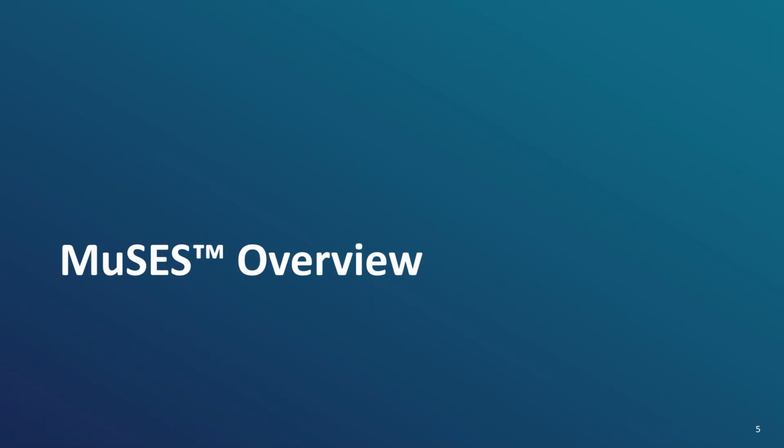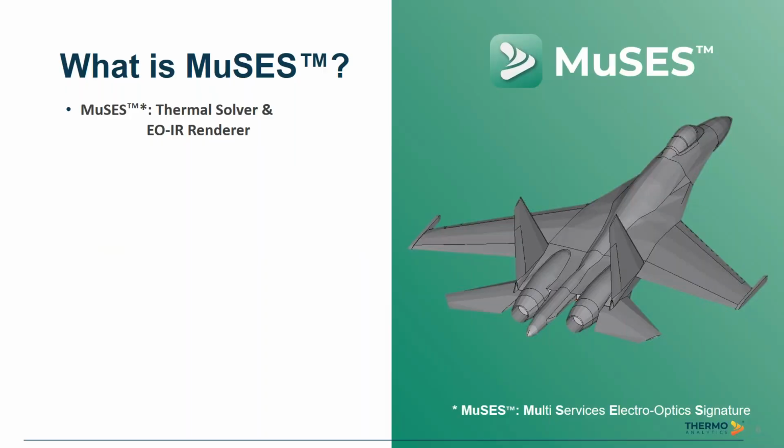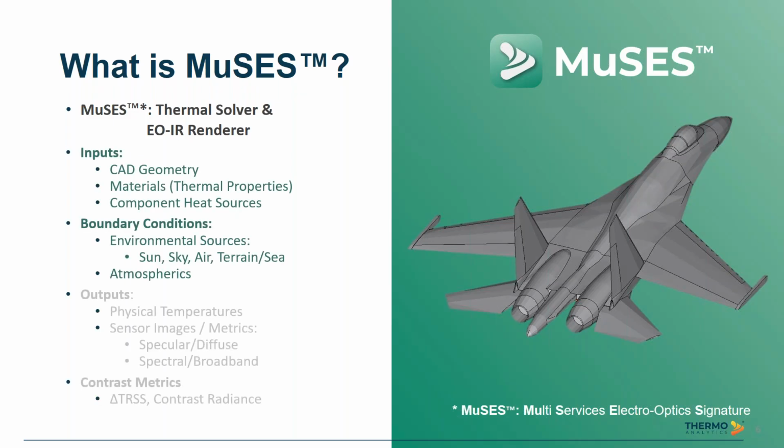To start, I'll give a quick overview of what MuSES is and how the software functions. Our flagship software, MuSES, is a thermal solver and infrared rendering program, which takes inputs such as a 3D CAD geometry description, part material thicknesses and thermal properties, and component heat sources, as well as boundary conditions such as the sun location, the sky, and the background for radiation exchange, air temperature, and speed for convective heat transfer to properly set up the analysis environment.